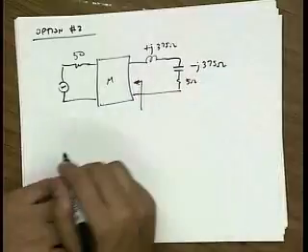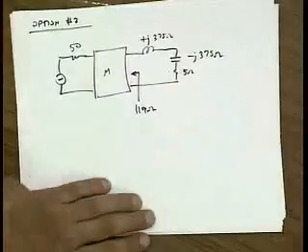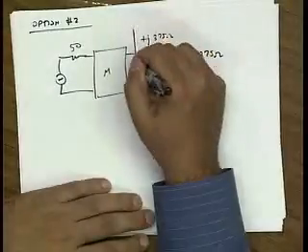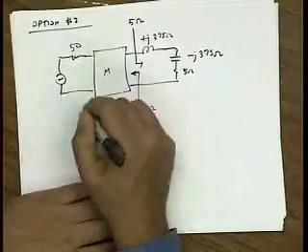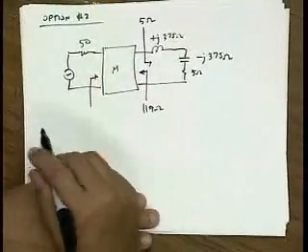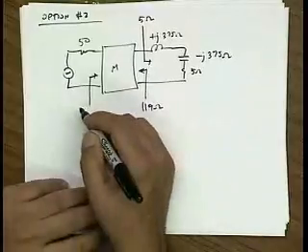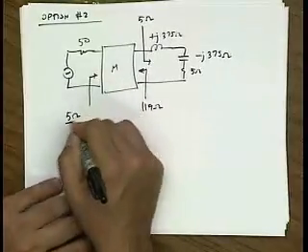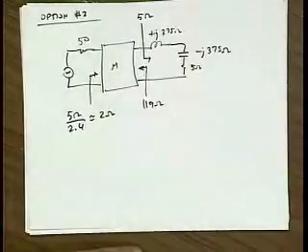I still use a matching network, so I get 119 ohms, so I get that great noise figure. But now, looking into here, I see 5 ohms at resonance, right? And this gets transformed down by a factor of 2.4, roughly. So looking into here now, I see 5 ohms divided by 2.4, or about 2 ohms.